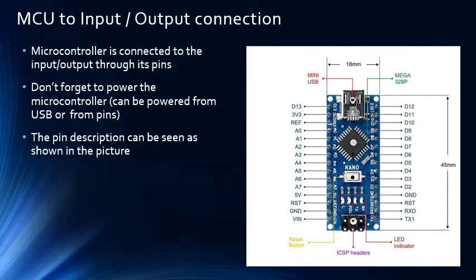If your input or output device only requires a low current, then you can connect directly to here. But if your input or output device requires a higher current, then you need to provide the power supply directly to the input or output device. Don't connect it to this Arduino. So okay, this is the input voltage.